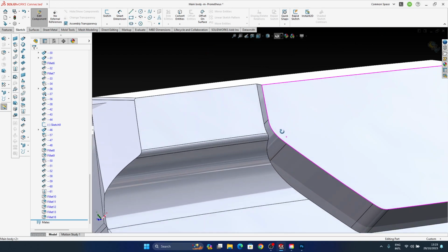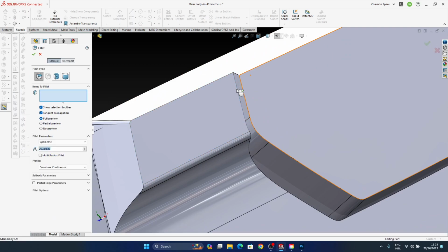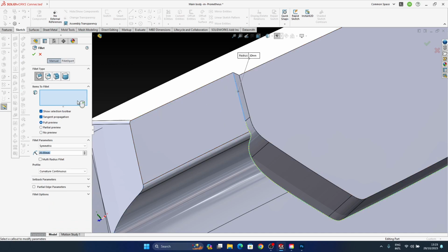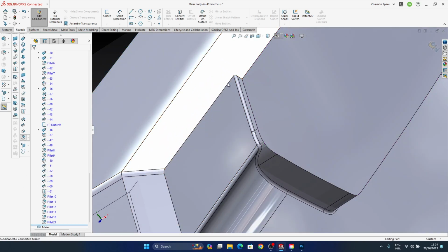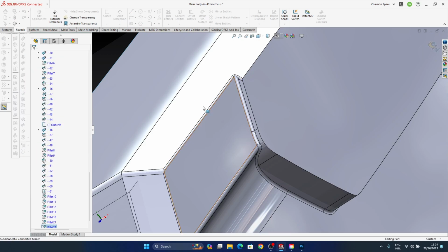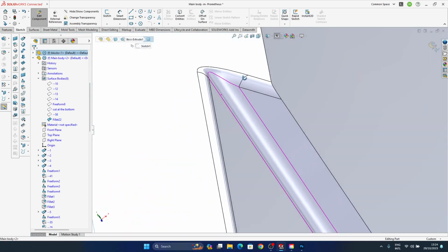And I think the compromise is by doing actually that fillet first. So not the surface, the edge. So if I'm building this like that, and then I'm going to apply a fillet in here, it should still get it kind of all right.